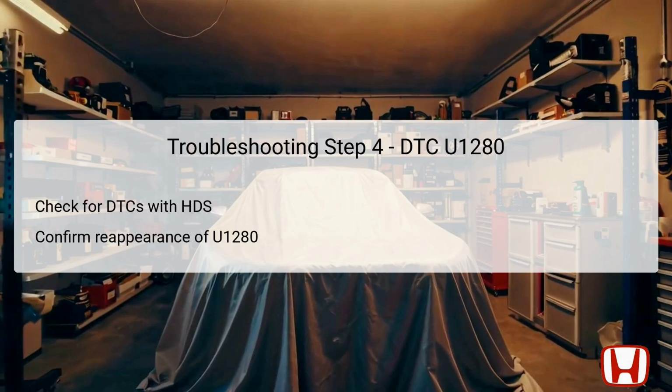The final troubleshooting step involves checking for any DTCs again using the HDS. This check will confirm whether DTC U1280 appears again after performing the previous steps and waiting for the systems to become operational. If the code reappears, it indicates a persistent issue, likely due to an internal fault within the beacon communication network or the components involved.